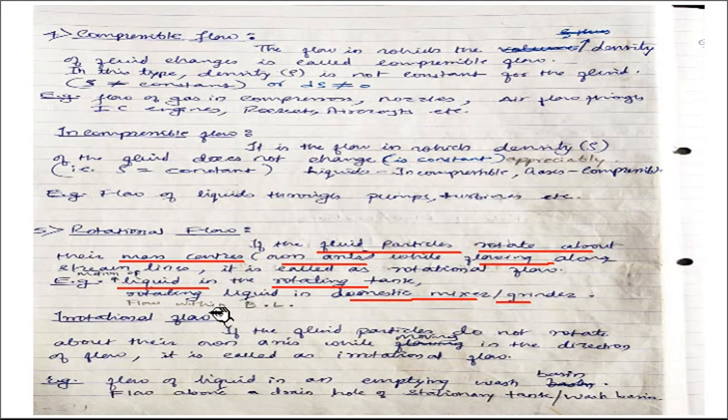A more mechanical application can be the flow of a fluid through the boundary layer which is formed over the solid surface. Inside a boundary layer, the flow has viscous effects. It is a viscous flow. So there is a presence of shear stresses inside the boundary layer. The viscosity is dominant, so that results in the generation of shear stresses, and that results in rotation of the fluid particles inside the boundary layer.